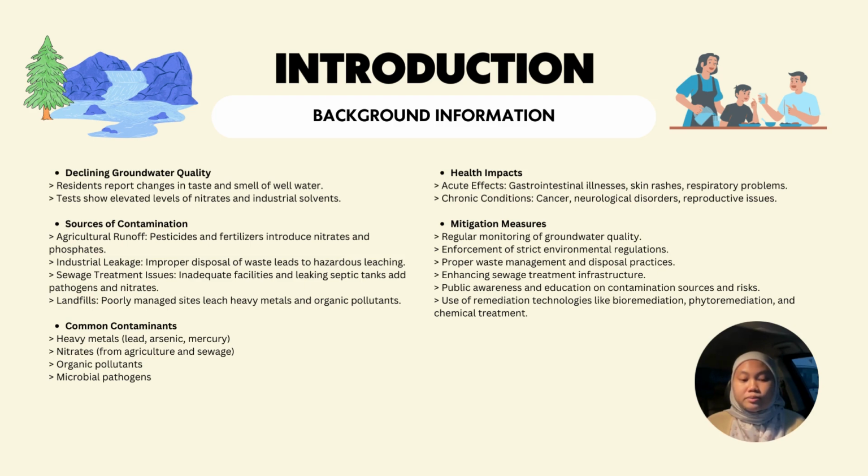And the second one is about the sources of contamination. In agricultural runoff, the pesticide and fertilizer introduce nitrates and phosphates. Industrial leakage and improper disposal of waste lead to hazardous leaching. In sewage treatment issues, inadequate facilities and leaking septic tanks add pathogens and nitrates. And in landfills, poorly managed sites leach heavy metals and organic pollutants.